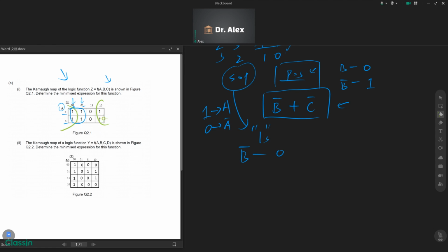These two rows at the rightmost will be formed with the leftmost 2 ones as another 4 ones group, okay? So for this new group, the two columns of A is 0 and 1.